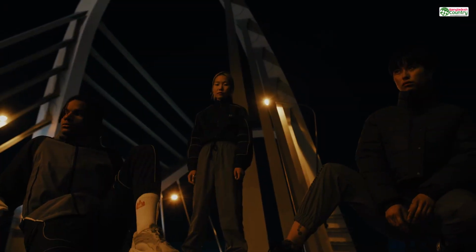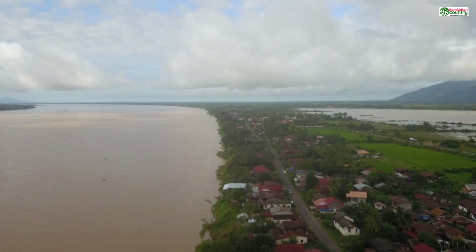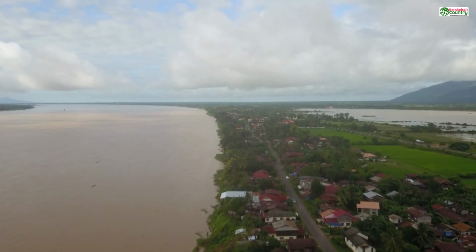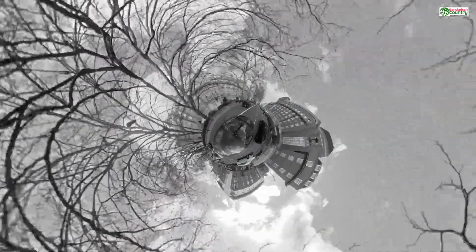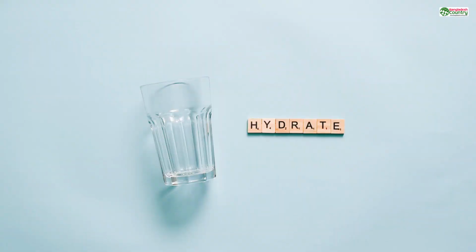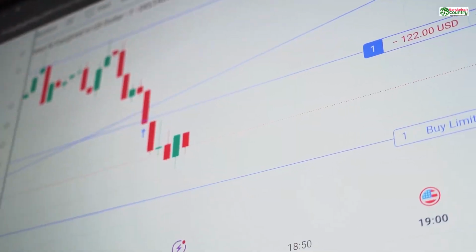So, when you upload your model to an online service, their software is going to analyze it for any angle steeper than that 45-degree threshold. It will then automatically recommend adding supports. You'll often be given a choice between standard and tree-like structures. Understanding this trade-off is key. You're balancing cost, surface finish, and structural integrity during the print.